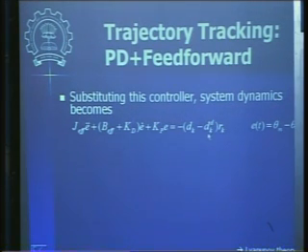Okay. So in general, once the transients are gone, the error between the trajectory and the actual motion will be very less, and because of that this term will also be very less. So that's how you can manage better trajectory tracking in this case. Okay, but this is also not perfect, you have not guaranteed zero error in tracking. Okay, it works very well for practical systems, there is no problem, but still theoretically some betterment of the performance can be done.